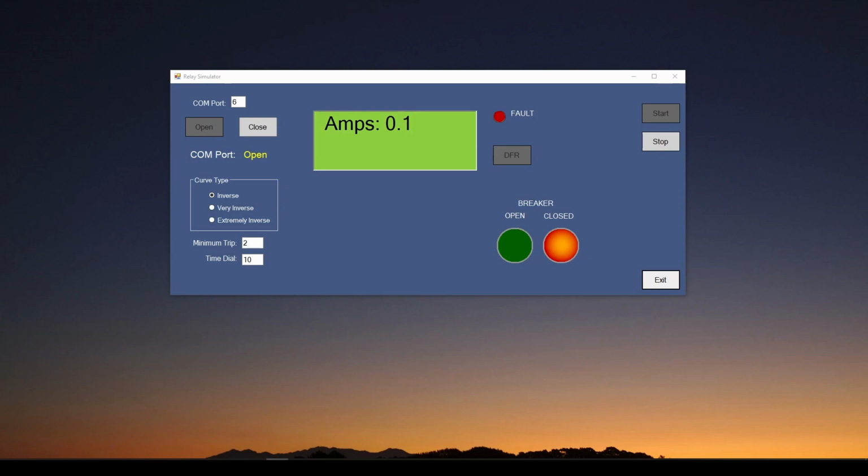And it's the job of the relay to detect if something's going wrong and then to open the circuit breaker that will turn off power to those lines, so that whatever problem it's having will go away and somebody can go out and fix the problem and then turn the power back on. But it's the job of the relay to monitor electrical power lines 24/7, and if something bad happens on the power lines, it's the relay's job to detect that, say, hey, something's going on, and perform some action like open a circuit breaker to de-energize that line.